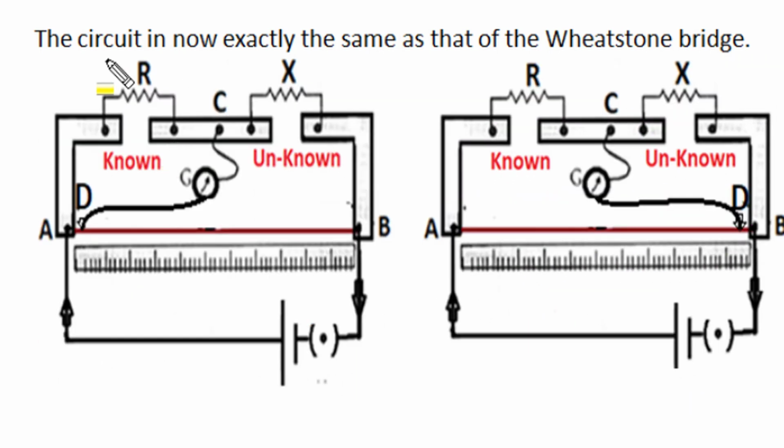remaining wire length. To check whether this meter bridge circuit is properly operational, to check proper connection of all resistances and source battery and regular functioning of this meter bridge circuitry, we place the sliding jockey contact very close to terminal A on the wire, and due to imbalance, the galvanometer will show deflection in one direction, and when the same jockey contact is placed at the other end of the wire, B, the galvanometer should show deflection in the opposite direction. If these two opposite deflections are given by the galvanometer, then we can say that all connections are in proper condition and the circuit is properly functioning.